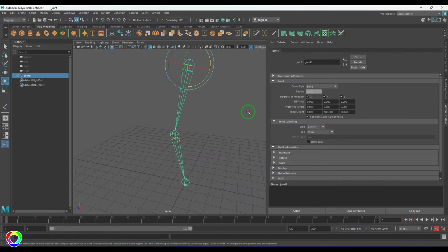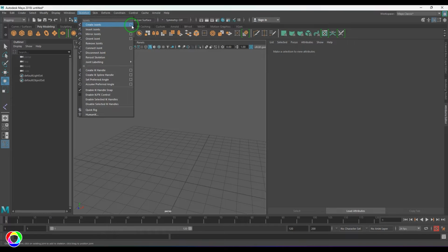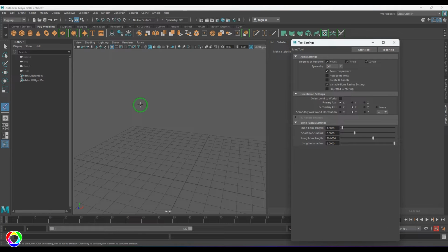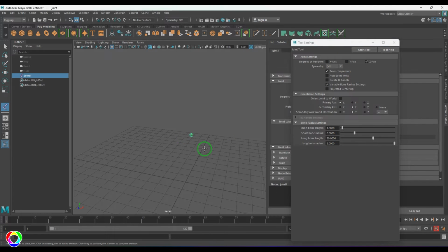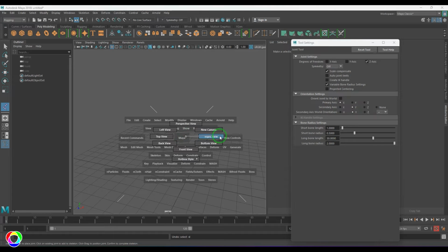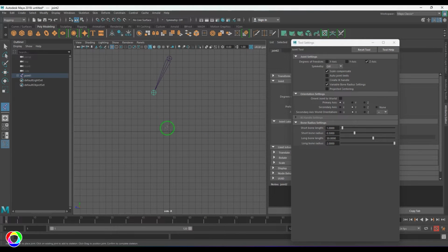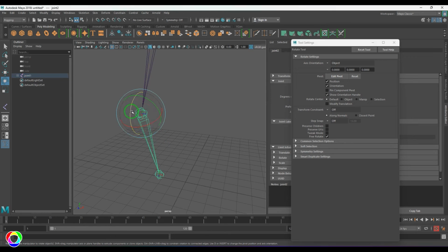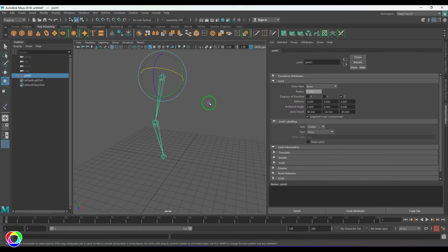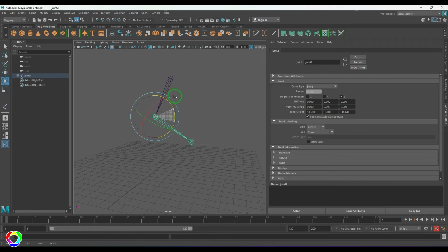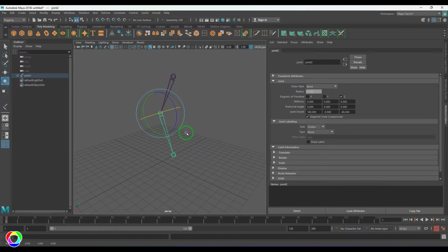It will be a great help when we are working with some joints, like your finger joint, which will only rotate in Z. It doesn't rotate to the sides, right? So you can generally choose this feature once you have created the joints. You can't rotate the other axes apart from the selected axis of freedom. So that's degrees of freedom here. It only affects that particular channel.